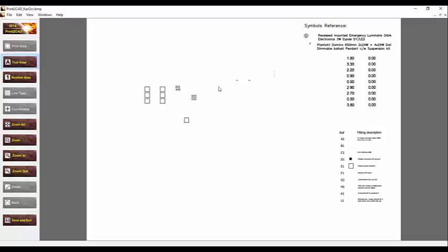Now the program separates, but you see a little bit more now, because the program now, the human being, tries to tell me what can be a text. And the program pre-separates everything that can be a text. For example, we take out all texts, all real texts, all long lines. And now you have to help the program. You can tell it, okay, here is a text with the same height. And here, so this is a text direction, you can see? Here is horizontal text with the same text height.